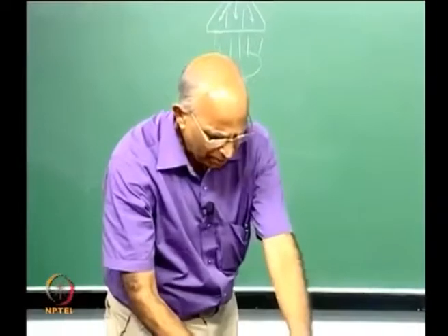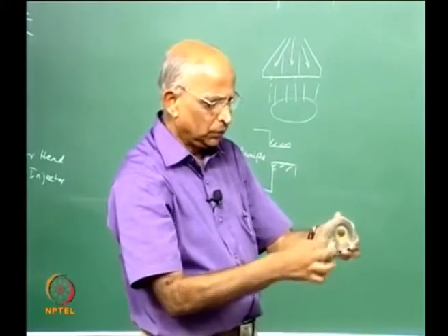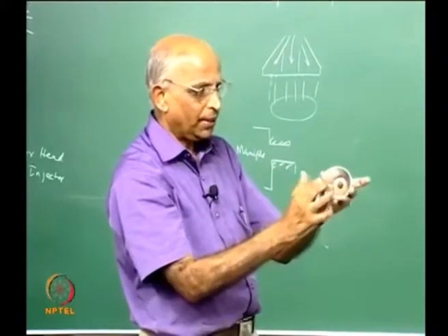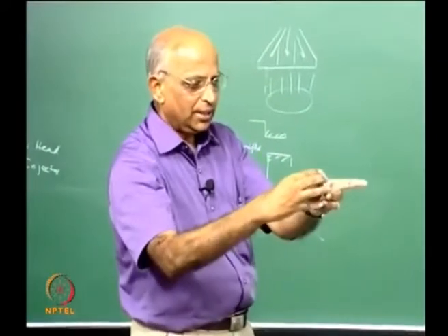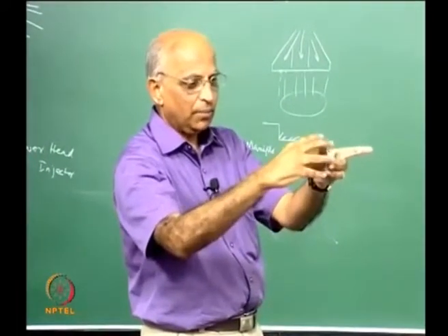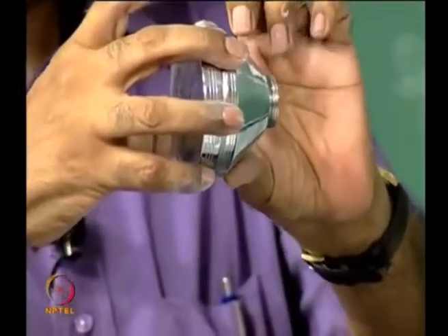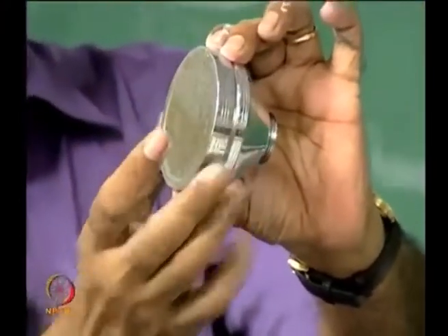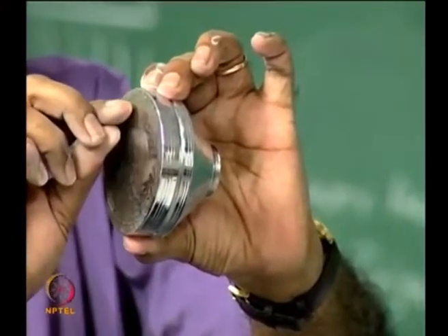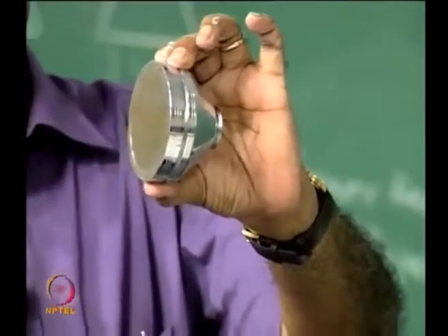I deliberately brought this because you are supplying water through this particular hole here, it collects in this particular manifold, that is, in the region in the chamber preceding the orifices. Therefore, the pressure in the chamber is the supply pressure, the velocity is almost 0, and then the water squirts out through these particular holes.